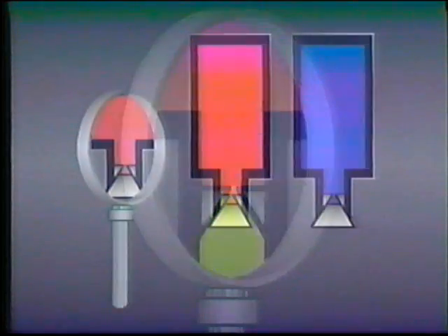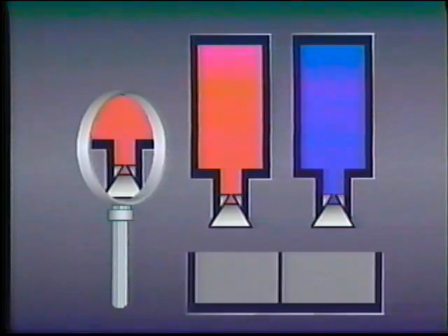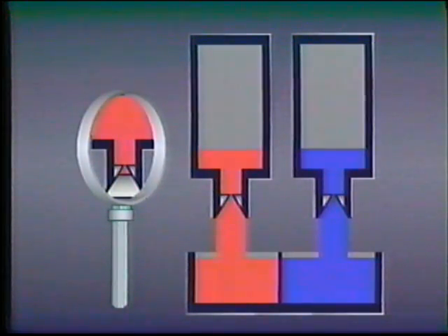More commonly, flow control valves use a sharp edge orifice for temperature compensation. Within limits, this type of orifice ignores differences in viscosity. Let's say we have two tanks of the same size with identical sharp edge orifices in the bottom. Hot oil is in one, cold oil is in the other. When the stoppers are pulled from the orifices, the cold oil will flow out just as fast as the hot oil. Precision-made sharp edge orifices provide very accurate control of flow rate, despite changes in fluid viscosity.